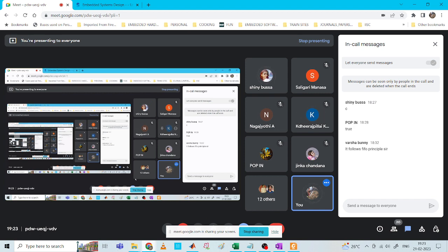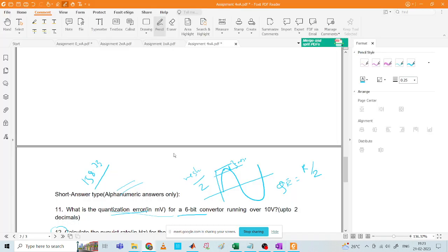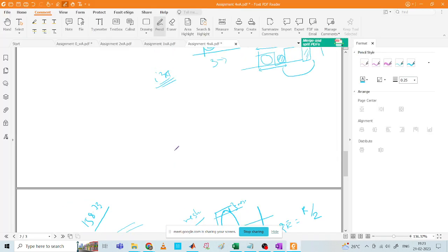So you have to understand the difference between Harvard and von Neumann. Let's say you have a microprocessor. The microprocessor will have an address bus as well as a data bus. The data bus is bidirectional, and the address bus is unidirectional. Now you have one single memory. This is a typical von Neumann architecture.